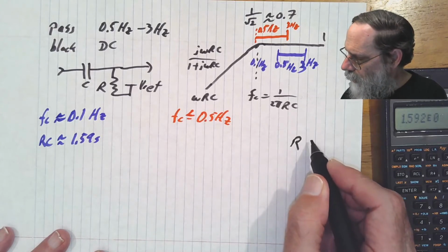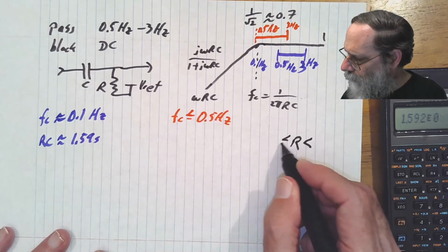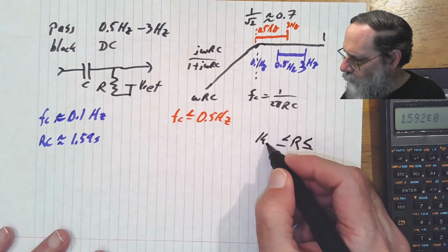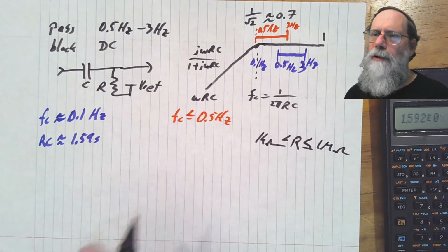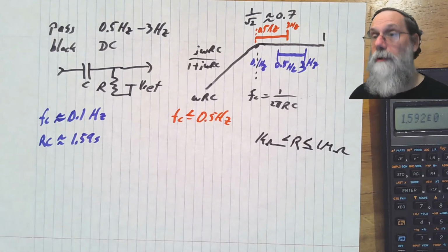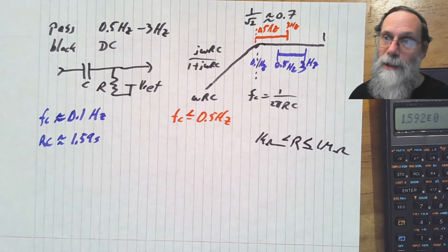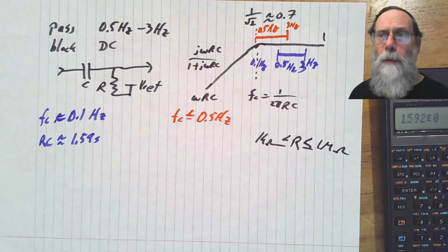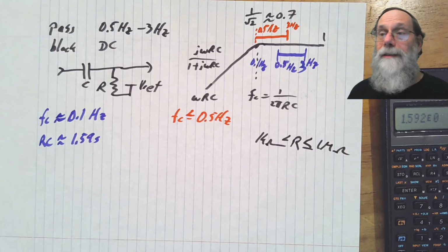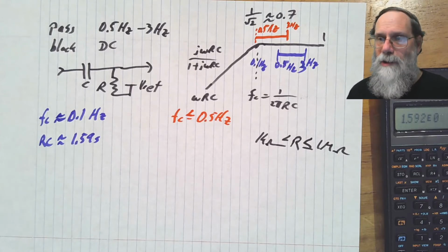So, rough rule of thumb, let's keep things, when we can, between 1 kilo ohm and 1 mega ohm. Now, those are not strict rules. Sometimes we'll go a little lower than a kilo ohm, sometimes we'll go a little above a mega ohm, but it's a good ballpark: if I don't know what size to use, try and keep it in this range. Factor of 1,000 there, so you still have quite a few choices.